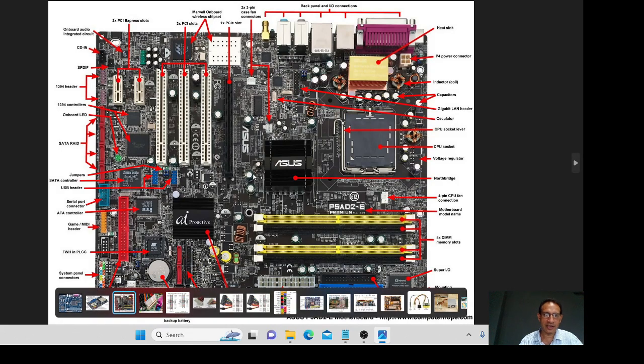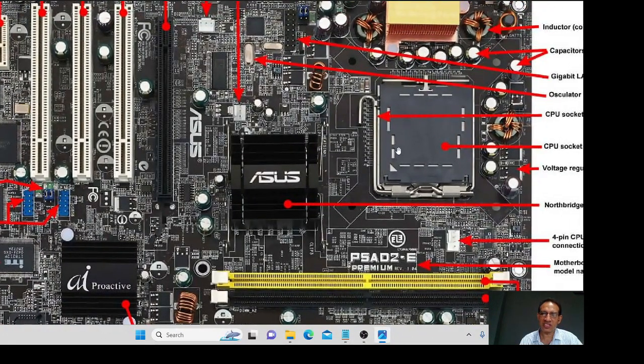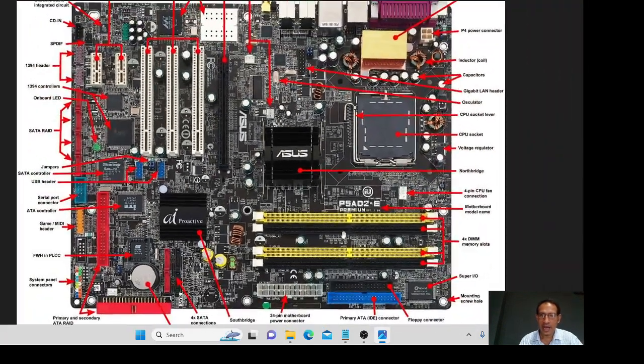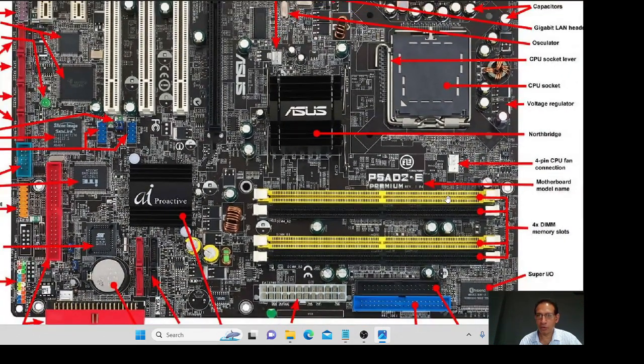this is the example of the ATX motherboard. A bit complicated because it is a sophisticated motherboard. This is the Asus motherboard. Here is the microprocessor socket. And here is the north bridge, and this is the south bridge. North bridge and south bridge are covered by the heat sink. That is why a black heat sink is there. And the memory, it's yellow color. The memory is dual inline memory modules, DIMMs, that means DIMM slots to use for the RAMs.